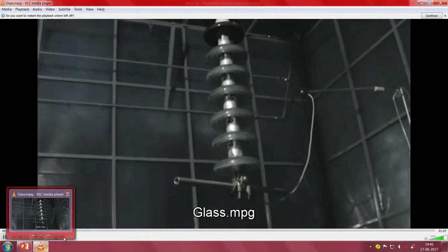We find the discharges from the conductor end towards the ground, the scintillations or partial arcs, will be observed initially. Later on, as the voltage increases, the stress across the string increases, and the conductivity on the surface of the glass insulator increases. A further increase in voltage will cause a breakdown or flashover across the entire insulator string. One such example you can see here.